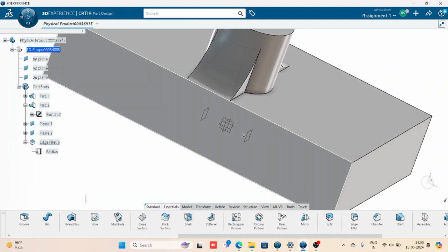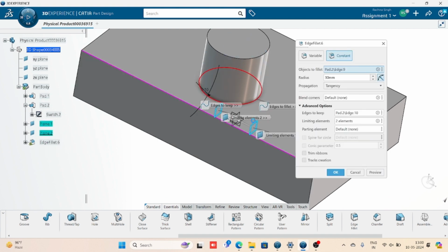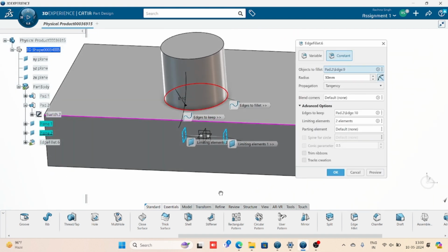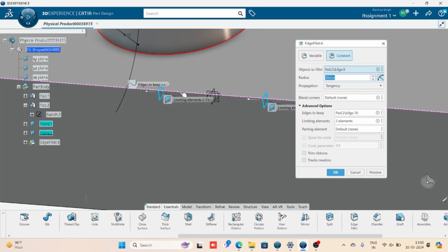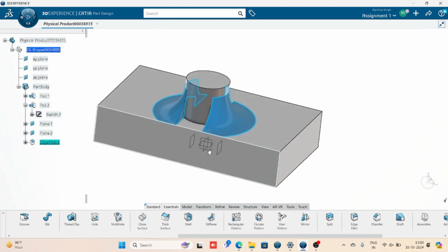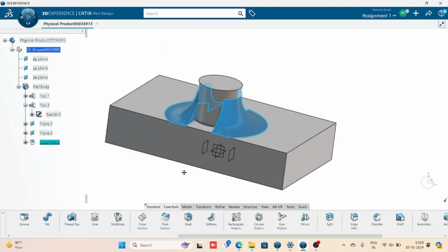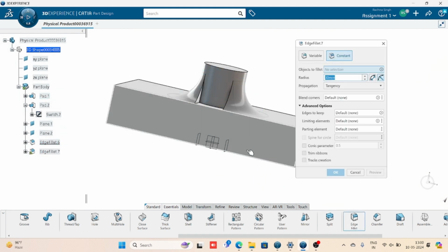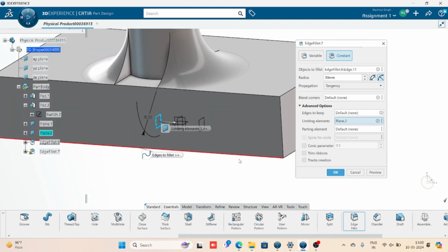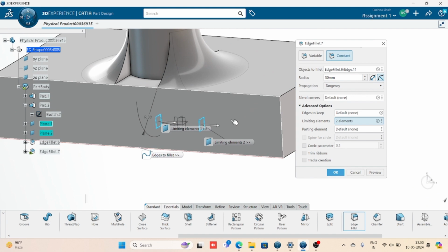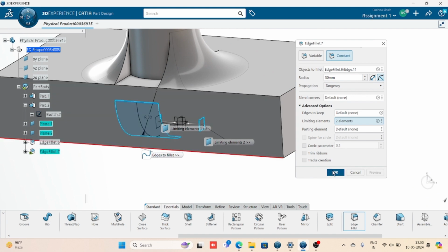But now I don't want fillet up to the limiting face, I want it beyond the limiting face. So in that case I'll reverse the direction for both the fillets. Here you can see it is quite simple, and this can be done for the edges as well. Like if I'm making an edge fillet and I have just defined limiting faces, the direction should always be opposite.